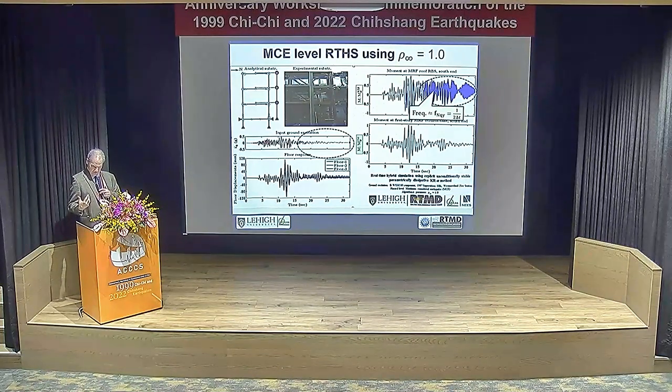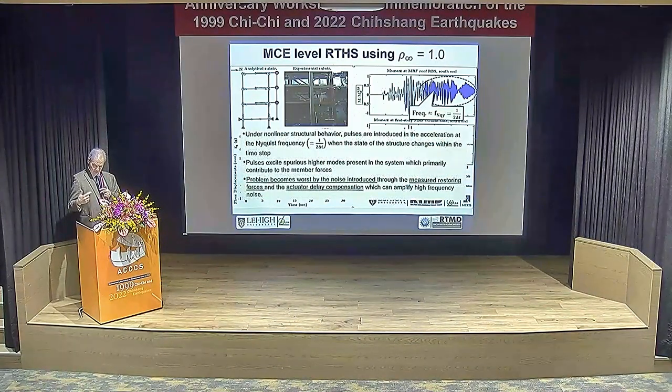It's like the Nyquist frequency. So it tells you something is associated with the time step, and what is occurring here is you're getting nonlinearities within the time step, and this happens in any integration scheme, particularly explicit. You're getting a change of state, which in the integration schemes causes an acceleration pulse, and usually it's at the higher frequencies. Well, that will attenuate downwards to the lower frequencies, but it's a change of state within the time step. And so these pulses will excite higher modes, and the higher modes are basically going to contribute to deformations because it's relative motions, particularly in rotations, that are going to cause or lead to the member forces.